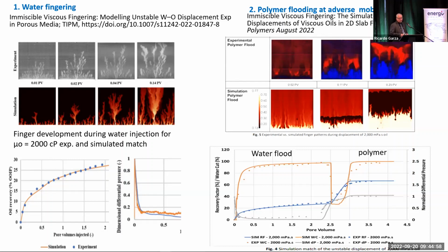So this process is going on, and what looks like an instability on the water is not an instability. It's a kind of piston-like frontal movement, because the black areas in between are areas which have already been swept by the water. So now you get a uniform front moving upwards with banking oil on top of it.